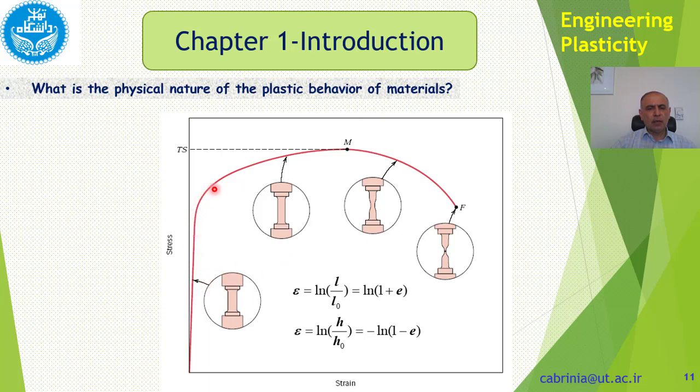As we go along, in fact, we increase the distance between the platens. The lower crosshead in the previous slide moves down, the length is extended, and the load is increased. Okay, this is the extension in length, and this is the increase in load. But we have shown this by stress and strain.